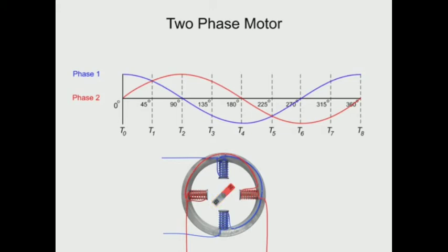Induction motors. Induction AC motors are characterized by a rotor which is neither a PM nor a DC excited electromagnet. Instead, current induced in a coil wound on the rotor generates the interacting magnetic field of the rotor. This current is induced from the stator coils.